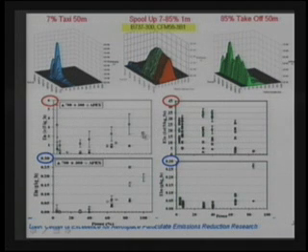This is the 50-meter data for all three engines, okay? And here we're at 1 meter, okay? And on this scale, all right, it's 6 times 10 to the 15 particles per kilogram of fuel. When we go out to 50 meters, there's a lot more scatter in the data. That's all being driven by the nature of the processing. Because remember, all of these points are all taken at slightly different times, okay? We've gone up by a factor of almost 8 here in terms of the number-based emission index scale. Whereas in case of the mass is dominated by the soot, and that's consistent with what you would get at 1 meter.